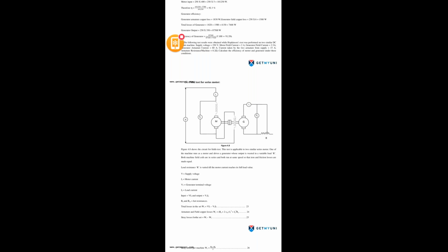Now here we are using three voltmeters. One is to measure the input voltage we are applying to the motor. That is the first voltmeter, indicated by V. The second voltmeter, V1, is connected across the series field winding and armature winding, and it gives the back EMF available on the armature winding of the motor. The third voltmeter is V2.